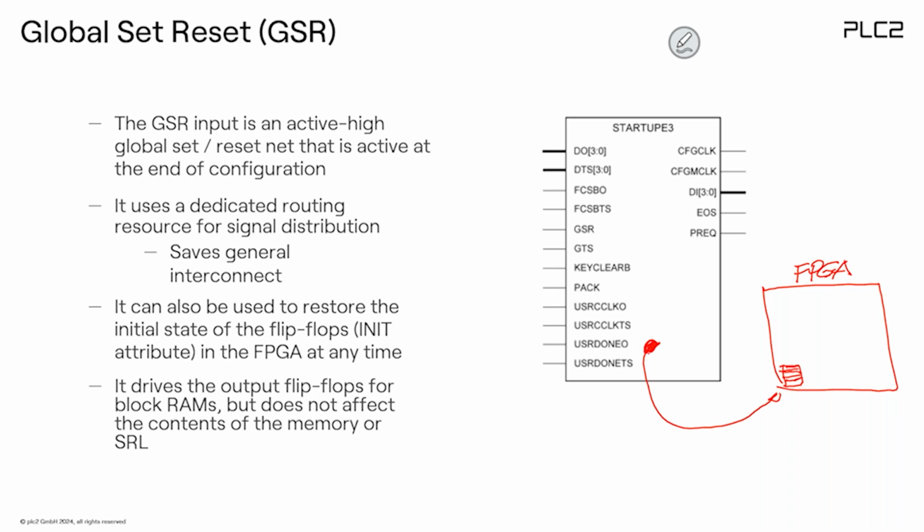This means whenever you switch on the FPGA and configure it, this startup block is connected with a signal called GSR, the Global Set Reset signal. It's connected to all the flip-flops, all the registers in your design. And if your configuration is done, this block is switched off and your FPGA gets initialized. But if you would like to have this function as a global function also during normal operation, you just instantiate this startup block in your design.